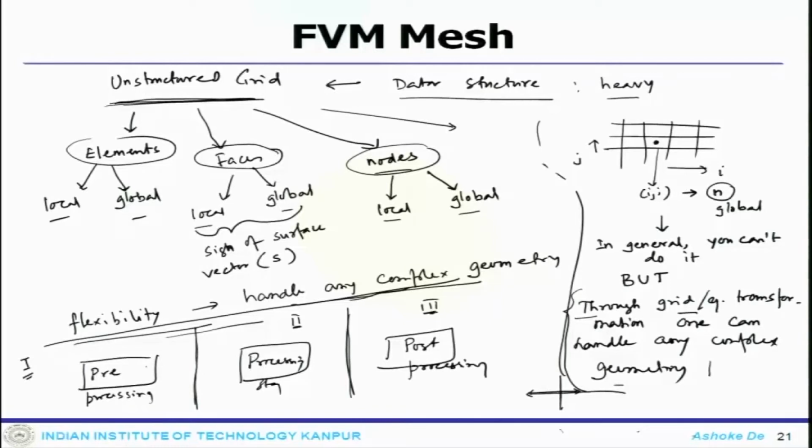Now, pre and post, that means the block 1 and block 3 consume the bulk of your time for the calculation done. From start to end, these two blocks consume a lot. Why? Pre-processing stage actually includes your domain definitions, in other words your domain modeling, physical modeling and all these things. So, essentially your physical domain needs to be transformed to your computational domain at the pre-processing stage.